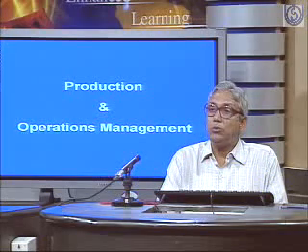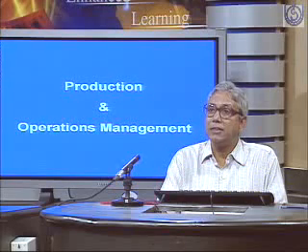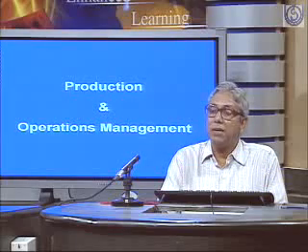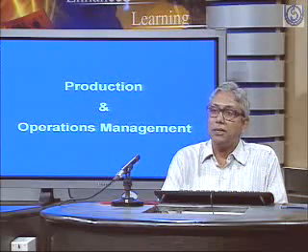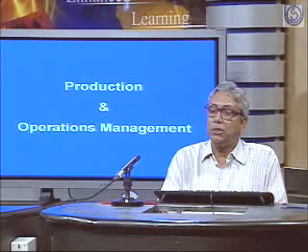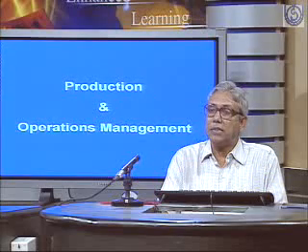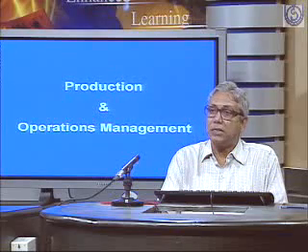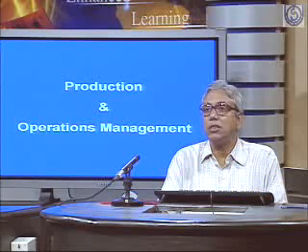Now, how to reduce that? So the production planning and control department will have a certain task: expedite the matter, find out why it is held up and for which component it is held up. Now find out at the moment where that component is, push it through, and try to complete this task as early as possible, so that at the earliest it reaches the final assembly or sub-assembly, so that they can complete this task. Some people are engaged for this, they call it expediting.